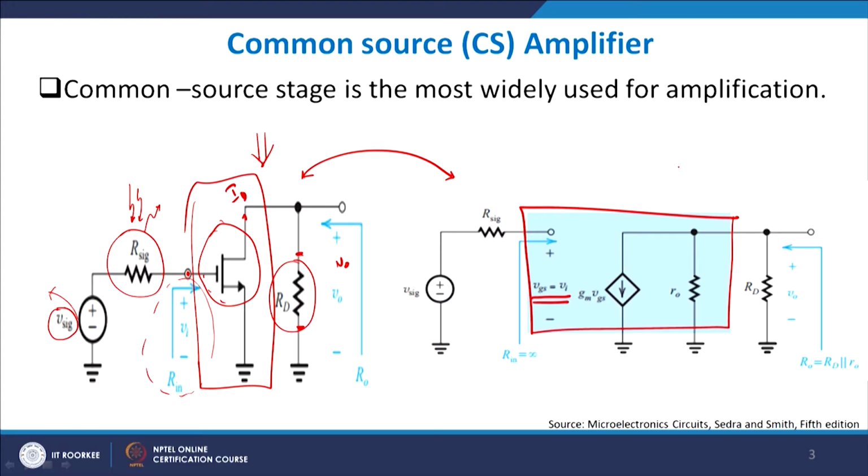We have also understood previously, when we were discussing the small signal, that I will always have an ro, which is the output impedance of the device, by virtue of the fact that your output will be slightly affected by channel length modulation. So, you will always have the channel length modulation phenomenon, and therefore, if you want to find del V by del ID, you will always have an r0 which is not equal to infinity, but typically a relatively large value, and that is what r0 is here.